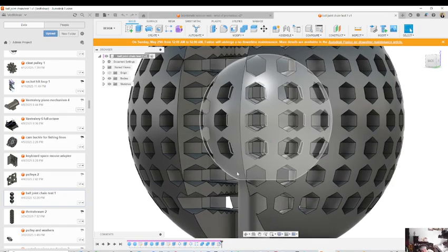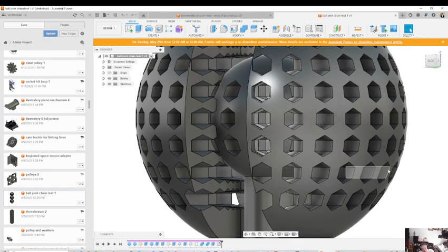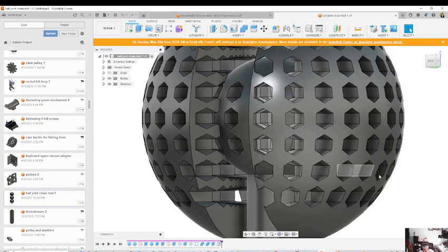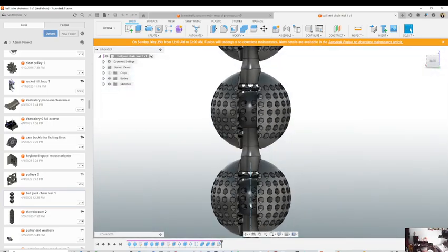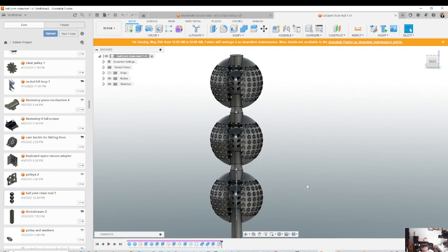So in my practice, I find that if you leave a gap of 0.5 millimeters for any part, regardless, the print is going to function mechanically with that kind of tolerance. But I needed to do a test like this to figure this out. Now I wanted to try this out and see if I could create kind of an omnidirectional joint, so I created this. That was an interesting test, but there is not that much to it.